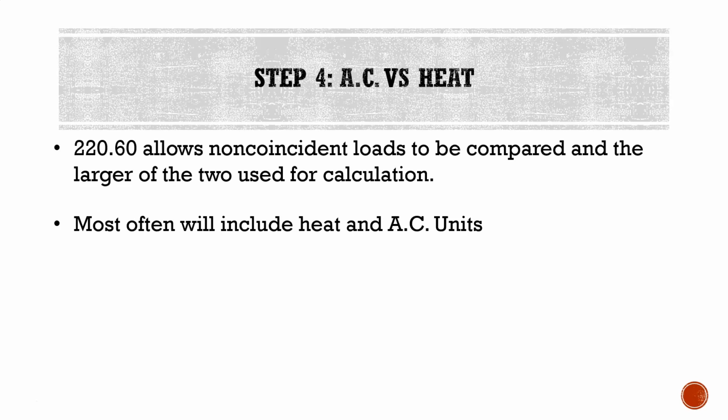So for this calculation, we had an 8 kW heat unit, which is how heat units will typically be displayed. A lot of times for AC, though, as we had in this situation, we have a motor load amount. We don't know what the kW is. So in order to establish which of those is going to be the bigger of the two, we would have to convert them to like terms. Now, we don't really have any way to convert a kilowatt amount to a motor size, so we don't have any choice but to convert that motor into a kilowatt size.